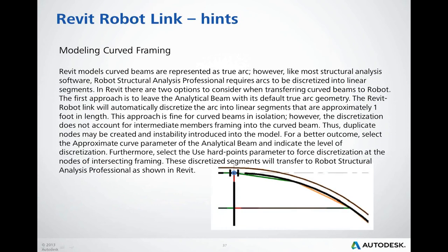Modeling hints can be found on slide 21, but here are a few words about curved elements. Revit models' curved beams are presented as true arcs. However, like most structural analysis software, Robot Structural Analysis requires arcs to be discretized into linear segments. In Revit, there are two options to consider when transferring